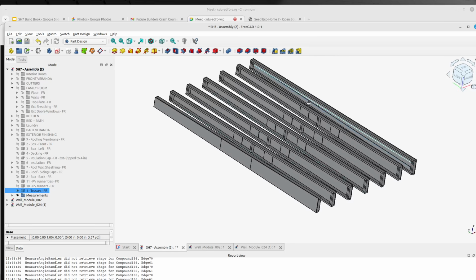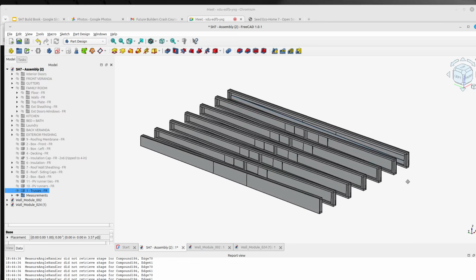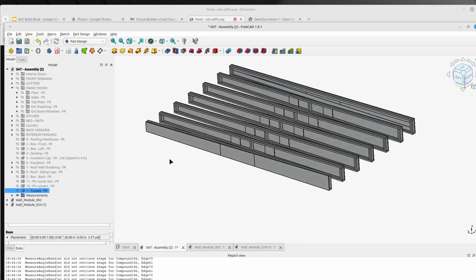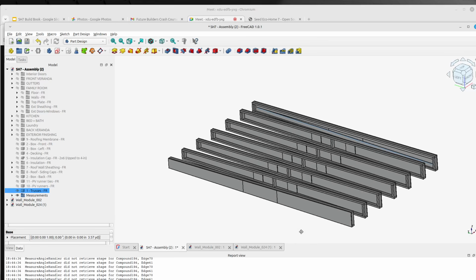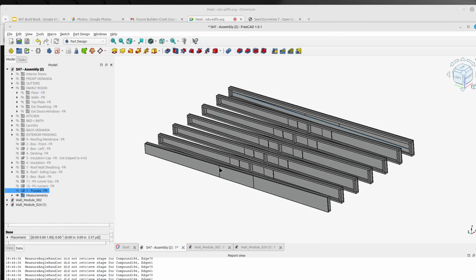If you're concerned about codes, yes, that's an issue. If you're in a coded jurisdiction, you need to pass this by the inspectors. We don't have that yet. We will provide engineering, but if we don't have the engineering, you need to fall back to the standard method, which would be, for example, 2x12 by 20s on 16-inch center. If we have the ability to pass the code, i.e. provide the reference drawings, yes, you can do exactly this.